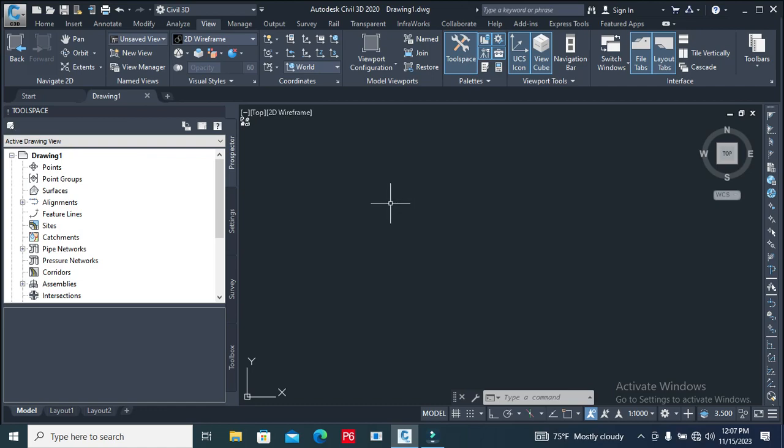The surveyor goes to the field, picks the data, and it's always better to arrange this data in northing, easting, and point elevation format, and all the utilities can be named by the surveyor according to a system that you want to use.